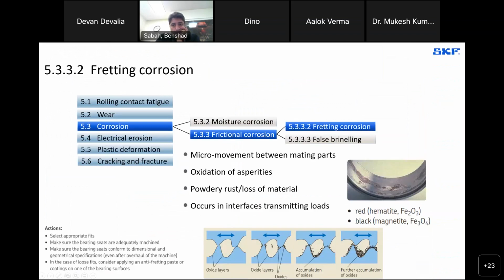When the bearing is under load, it gets squished and it grows. Part of the reason for the fretting corrosion on a stationary outer ring is not because the outer ring is creeping, but because it is growing as a result of being compressed under load, and it's doing this cyclically. So you will have fretting corrosion underneath.